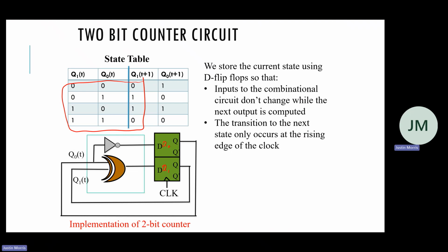This is just a truth table, right? It has multiple outputs, but you can just look at them individually. Like if I wanted to figure out what's the combinational logic to implement in order to update Q1, I just make a truth table like this. And then if I drew out the K-map, I would circle these together, right? And I would find that, well, actually they would be individual circles, but I can implement it with an XOR gate, which is just A and B naught or B and A naught, right? And then you could do the same thing for Q0, right?